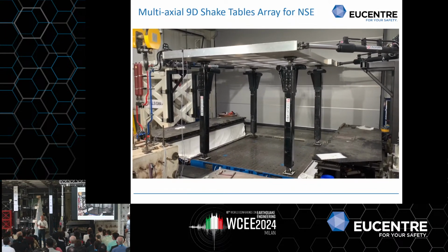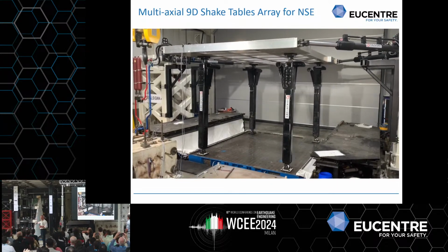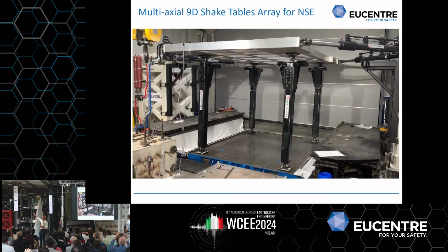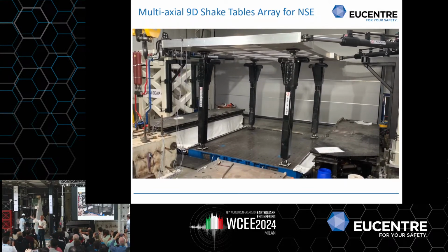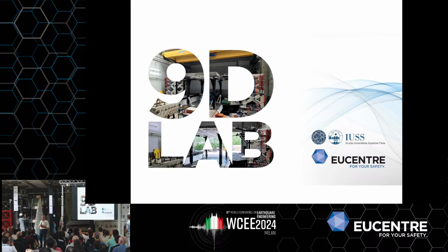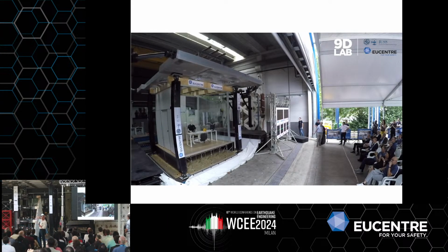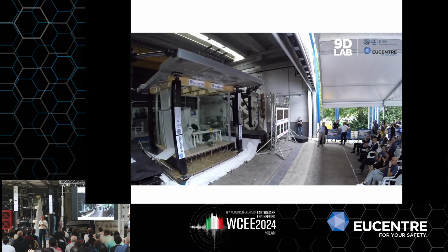Under this respect, this is a special kind of non-structural elements, but imagine that we could have an elevator, a pipeline, we could have non-structural walls connecting the 2, we can have a glass window, and this means that we can control independently acceleration, yes, but more than anything else, relative displacement. So we can have a relative displacement which is in this direction, and then have an acceleration in the other direction, which is what happens in reality.